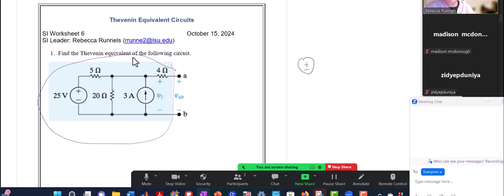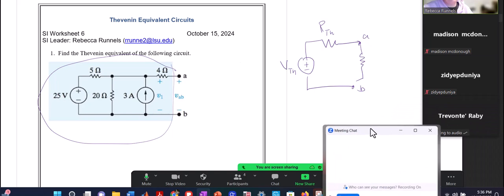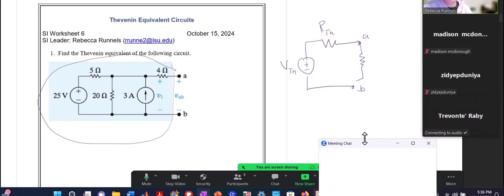So if you could say all the rest of my circuit is equivalent to this voltage and this resistance, if you can break it down to that, then you can put whatever item you're testing in here and use it. And so having the Thevenin equivalent can simplify things.